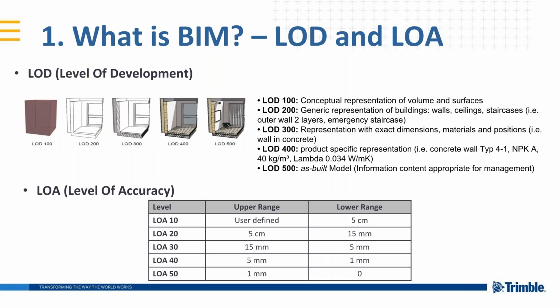Another point, just a couple of slides and we are done with the introduction and we move to the practical part. Also important to know is what LOD and LOA are. Once you get the project requirements or the tender specifications, you will always see these two acronyms. LOD is the level of development, which really means the level of detail that you have to provide your models with. Depending on the country, we have different levels, between 100 and 500, or in the US, for example, you have an additional one, 350, or there are others between 1 and 4, but it means the level of detail.